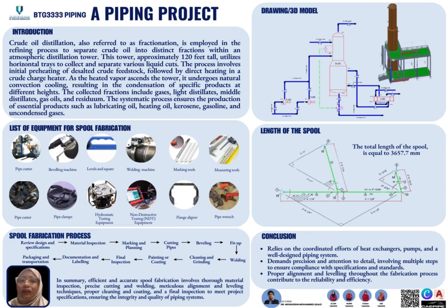Fourth is cutting pipes. We then cut the pipes to the required lengths, ensuring precise measurements and clean edges for a seamless fit. Fifth, beveling comes next, shaping the pipe ends to the specified angle and length. This step ensures robust joints and better welds.